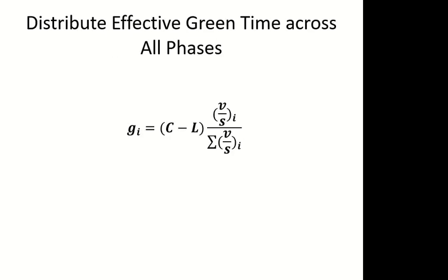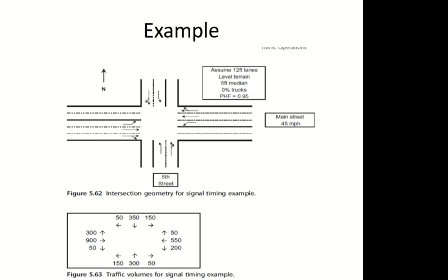The second step is identification of lane groups. Now east west lane movements are same, north south lane movements are same. So tell me how many lane groups in east west and how many lane groups in north south. In north south you have two lanes, right? So you can have one lane group or two lane groups. In east west you have three lanes, so you can have one lane group, two lane groups, or three lane groups. So which of these we have? In the north south, do we have one lane group or two lane groups?